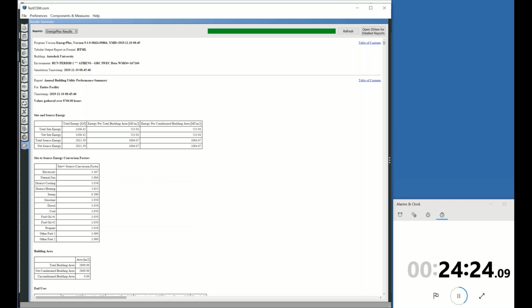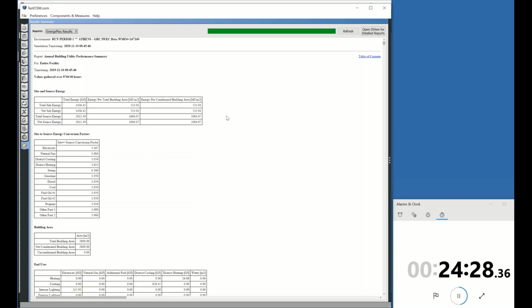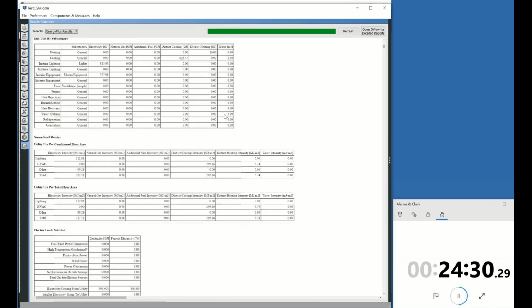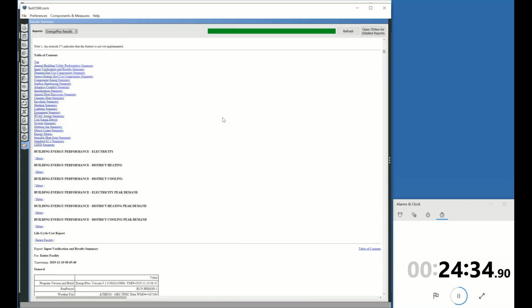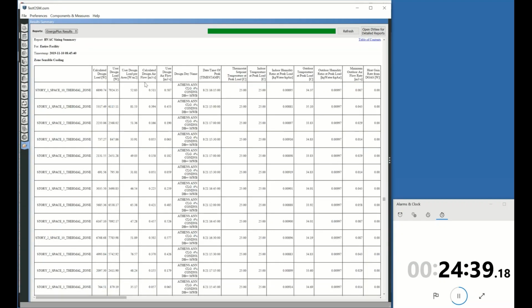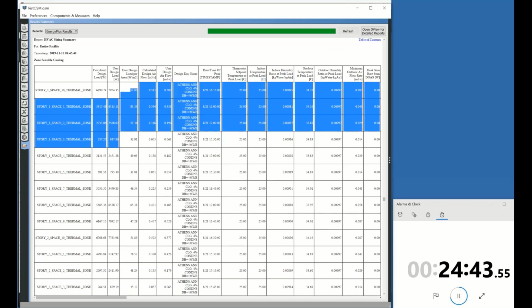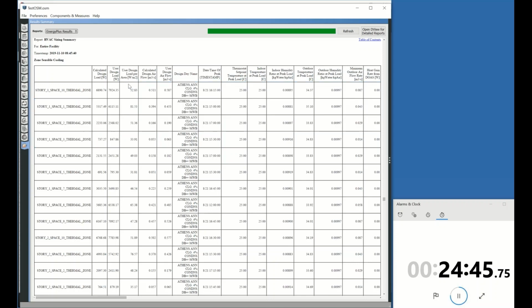So it was done. So now you can get the report as usual from EnergyPlus. So you have all the data that you need. For example, the HVAC sizing summary is right here. And you can see these are the numbers that we are using, the user design load per area, let's say, for the cooling. But you can also open what they call the DView data viewer.